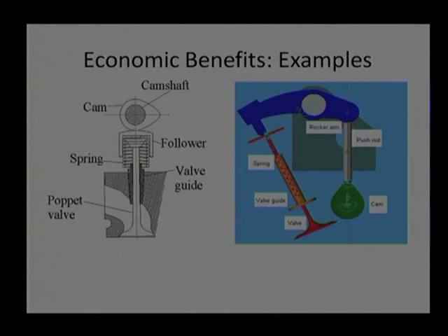That was replaced with the overhead cam technology, where now there is a cam, there is a follower and directly the valve. So, all intermediate links have been removed. We know very well, if we remove intermediate links, one, the reliability of the system is going to improve. In addition to that, a number of tribo pairs have been eliminated, so friction loss will be reduced.